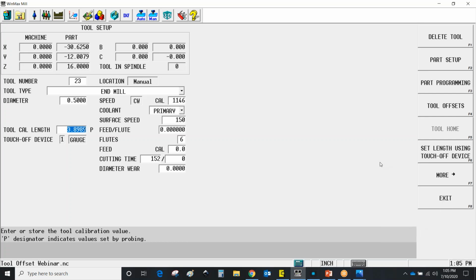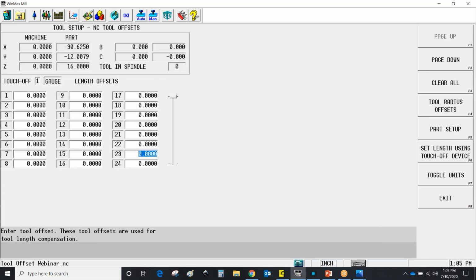But in most cases, once you've called the tool number, you call the H value, it's the same and you leave it alone. So if the shop that you're in doesn't need to ever use these H values, you have a couple of options. You can strip that from the program, so the post will never post out a G43 with an H value. So you can change the post. You can go in and hand edit the code to remove that. That way it will never look at this table, and you won't have that problem because the call out for it won't be in the program.